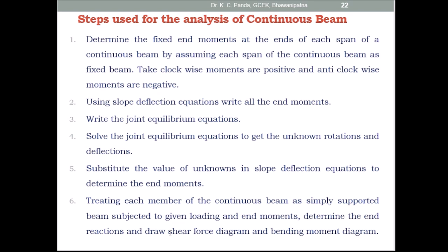Then find out the shear force values at different positions. Then draw the shear force diagram and bending moment diagram. So these are the steps used for the analysis of a continuous beam or rigid frame.